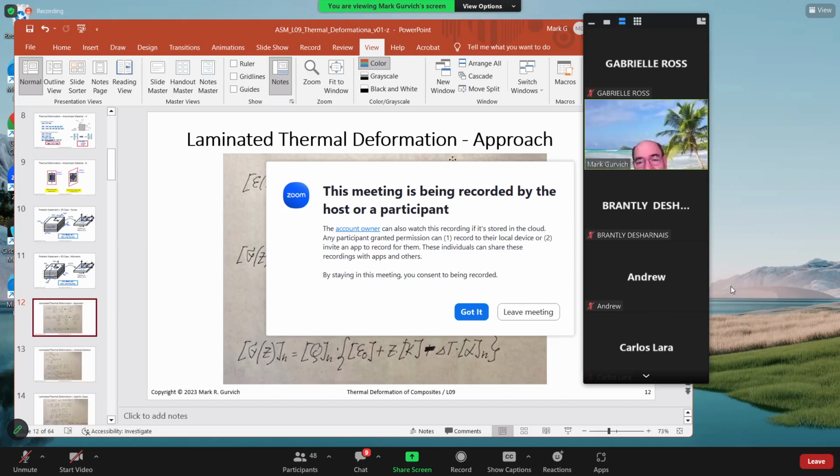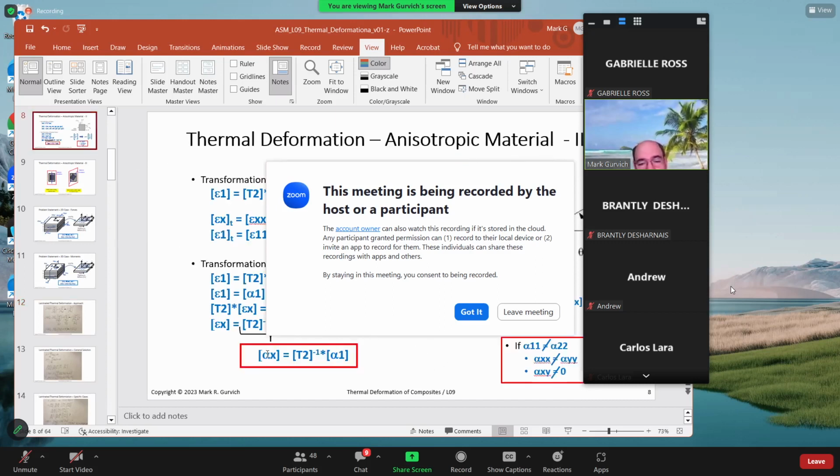So this component is actually what we calculated here, yes? If we know orientation XY, and we know material orientation 1, 2 defined by angle alpha, for each ply, for each layer, we can calculate those properties, alpha sub X, which are defined by this one-dimensional matrix with 3 components.